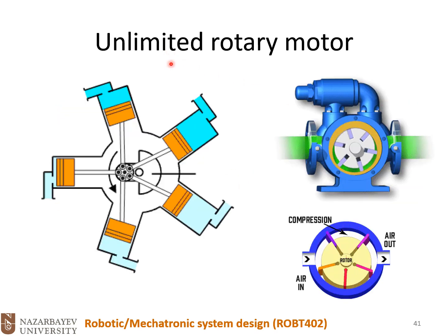Another type of rotary actuators are those with the unlimited range of motion. They have a different internal mechanism. This one, we are using multiple linear actuators and the crank. And on this one, we have multiple blades, very similar to those with vane cell.